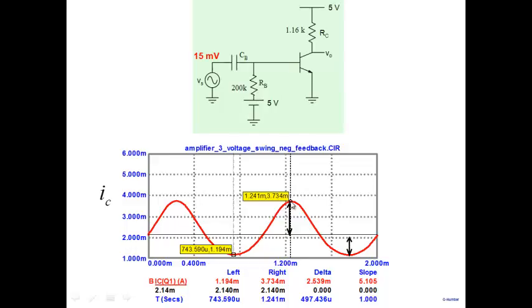Suppose I want to get rid of distortion, what should I do? This distortion which is inherent in the transistor. Yeah, I don't want to touch VCC here. The design is fixed. Suppose I say the following. Are you noting the following? I get a pure sinusoid here, right? I apply a pure sinusoid between base and emitter. This is a pure sinusoid, and the collector current is a distorted sinusoid.